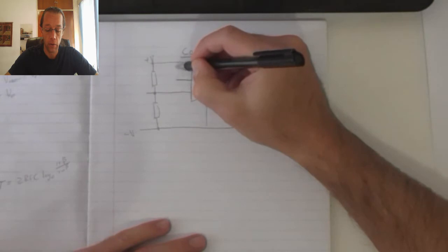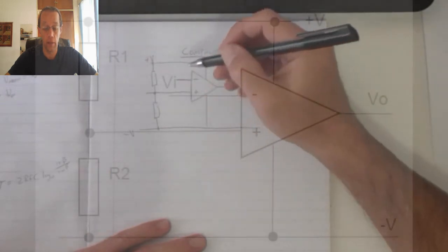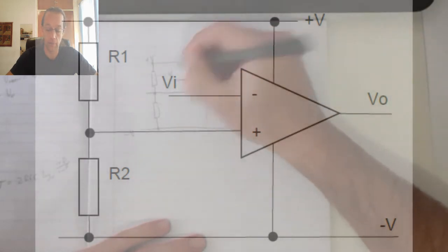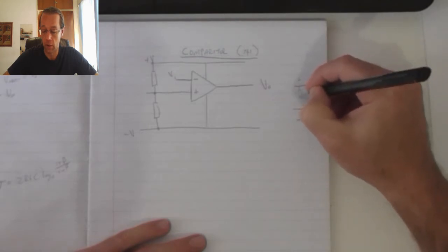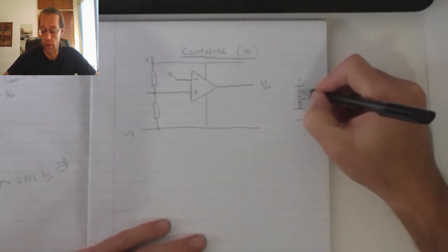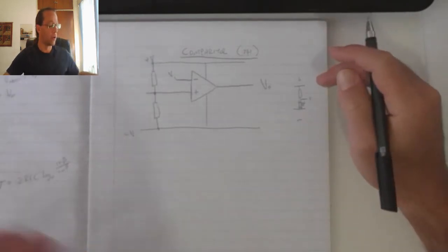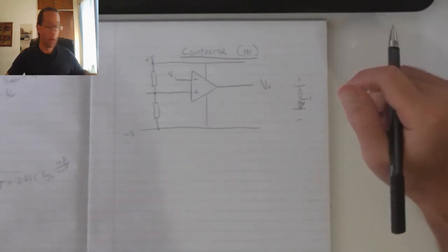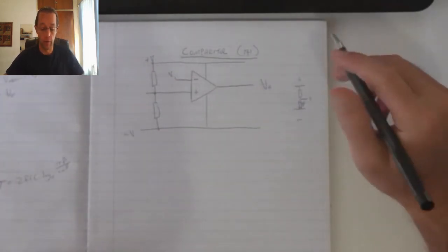This input also connects between the positive and the negative supply, but in the sense that we will have a sensor somewhere, either on the top there or the bottom there. So that's my V in, and V in will connect between the positive and the negative, between, let's say for example, a resistor and a light dependent resistor. Other possible devices that can be used are thermistors or strain gauges, but any device that changes its voltage according to external influences.